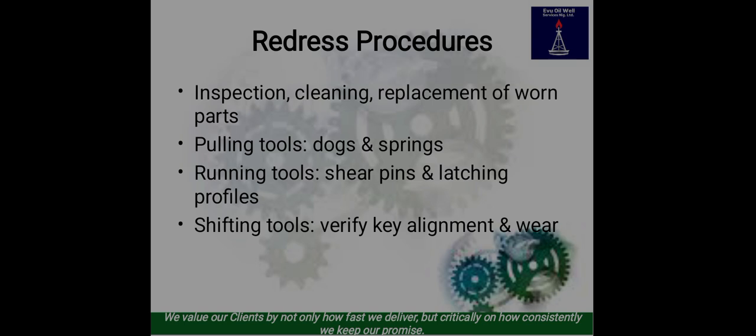Steps include: disassemble the tool, clean thoroughly, inspect for wear, tear, and damage, replace worn-out parts such as dogs, springs, shear pins, seals, reassemble and test function correctly. Redress is compulsory. It ensures tools don't fail downhole.